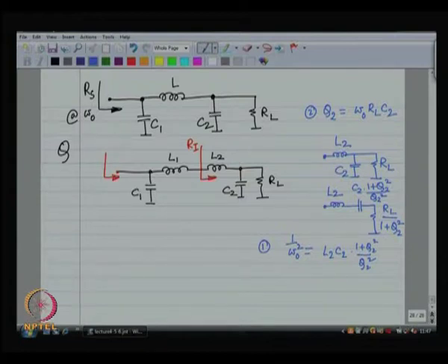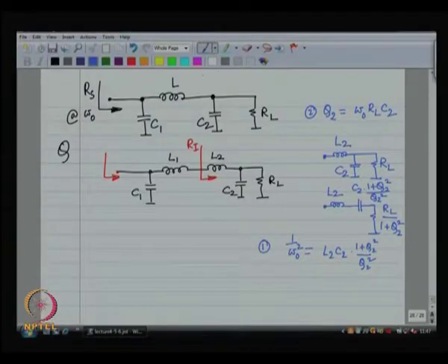Now, next, what am I left with? I am left with a resistor. Suppose the inductor and capacitor resonate with each other at omega naught, then the series combination of inductor and capacitor has 0 impedance, it becomes a short circuit. So, as a result I only see the resistance R L by 1 plus Q 2 squared. So, at omega naught what I see is as follows.